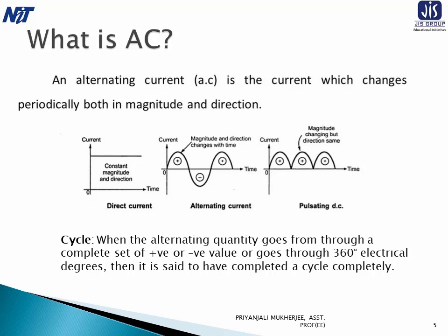And for industrial applications of direct current, which are the electrolytic process, welding process and variable speed motor drives, the present trend is to generate AC and then convert it into DC by converters.